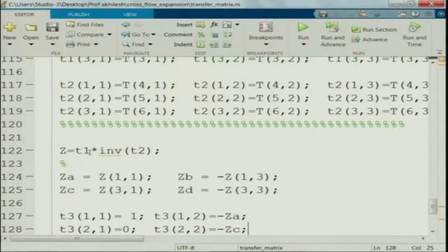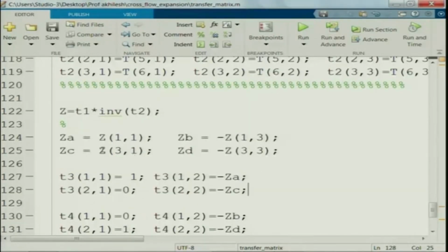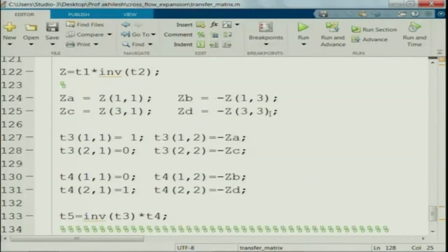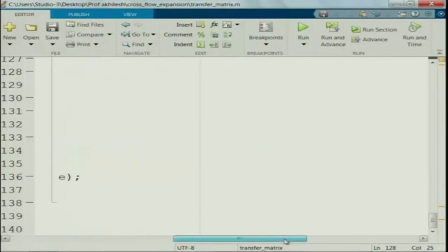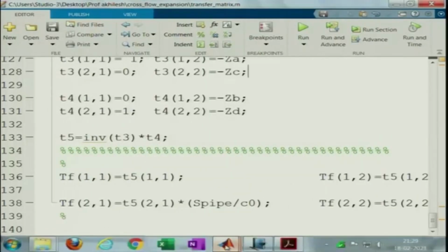So, once we extract certain rows and columns from the T matrix into T 1 and T 2 matrices, this is really the inversion thing that I was talking about, and this is really your impedance matrix. It relates pressures at different ports, namely at port 1 and 3, to the velocities at ports 1 and 3. Now, you get these things. So, these are all conversions of the impedance matrix into transfer matrix. We need not do that when we come at a later stage of the course, maybe next week or so, but for now I am just writing down a piece of code which essentially transforms the impedance matrix parameters into transfer matrix parameters, P 1 and rho naught C naught U 1, and then we get this kind of a thing. Okay. So, now I am good to run the code.